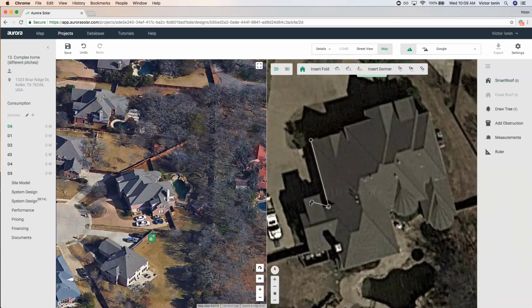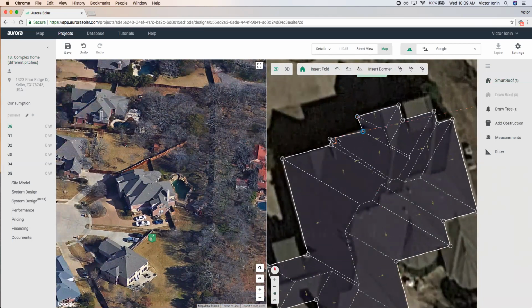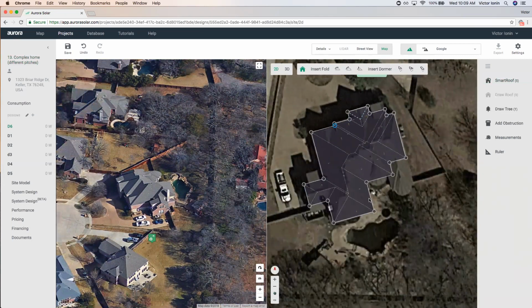All right, let's go ahead and outline this roof. So once again, shed dormer, ignore it. You'll notice there's a lower level here, ignore that. I'm going to ignore this piece here, draw it in separately. Ignore the lower level, draw that in separately. I notice that there is a shed dormer here, so we'll use the shed dormer tool. Whoops, I didn't snap that really well, so once I'm done, I'm going to go in here. Let's go ahead and fix these lines. I do want them all to be 90 degrees from each other. All right, so that's what we're going to get.